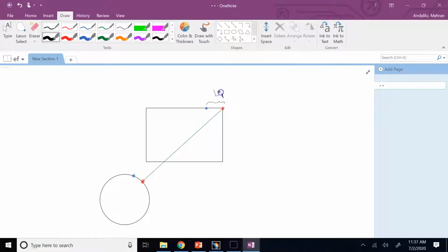L1, okay, the length of the arc between these two is L1, and then the entire perimeter of the rectangle is P1. So P1 is the entire perimeter of that. Then the entire perimeter of the circle is P2, and the length of the arc between the new point and the old point on the circle is L2. The ratio of L1 over P1 should be the same as what? L2 over P2. Okay, this is called the ratio coupling.